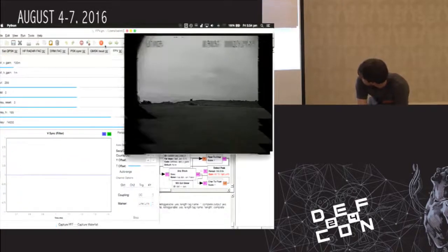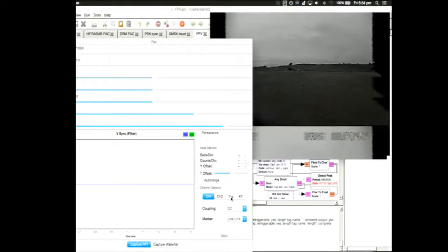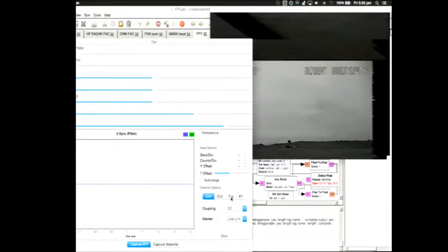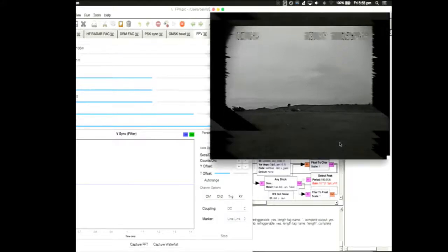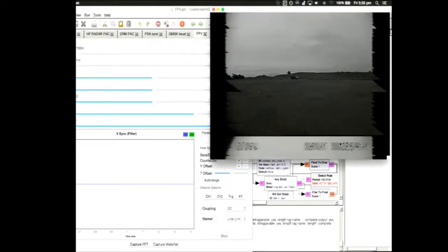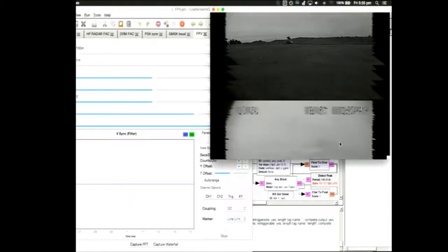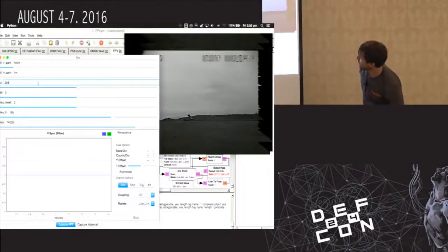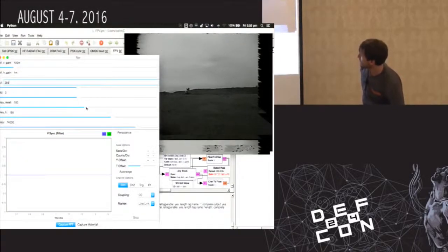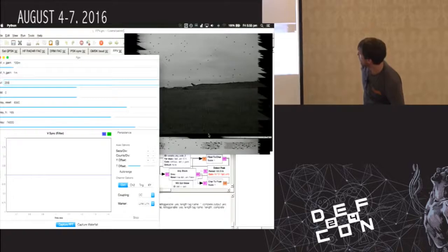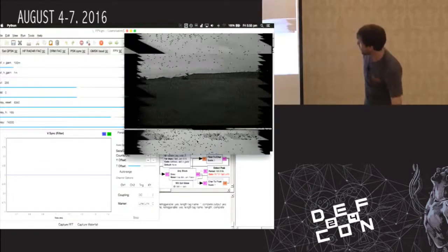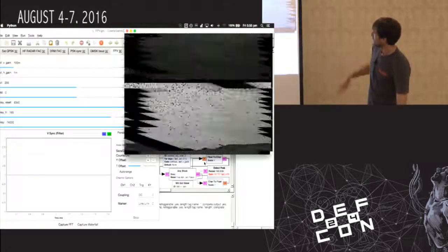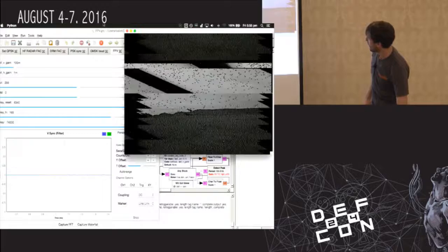Effectively, this is an NTSC waveform coming in, and I've got two matched filters that look for the vertical sync and the horizontal sync, and then it tries to line everything up and give you a picture. I didn't actually see color burst in this one, so I didn't have any color information. I'm just plotting luminance information anyway. But usually I've found that I just have to tweak the timing on some stuff. There are some weird blocks that I had to add, like certain things to look for peak detection, and whoa. But it's kind of getting there.